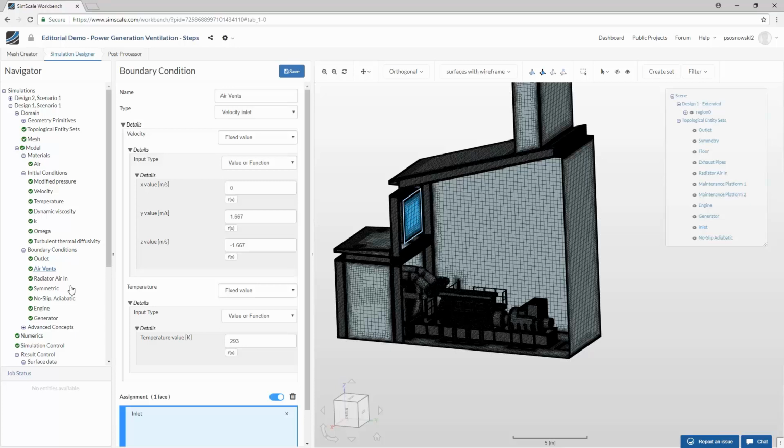Yes, so a rule of thumb I would apply when choosing the amount of cores that you calculate with is, whenever your mesh is bigger than 10 million, I would go with 96, or the maximum number of cores. If your mesh is around 4 million elements, you go with 32. 2 million is good for 16 or 32. For 1 million mesh cell volumes, you go with 8 to 16 cores. And to be honest, I never go below that. So, yes.